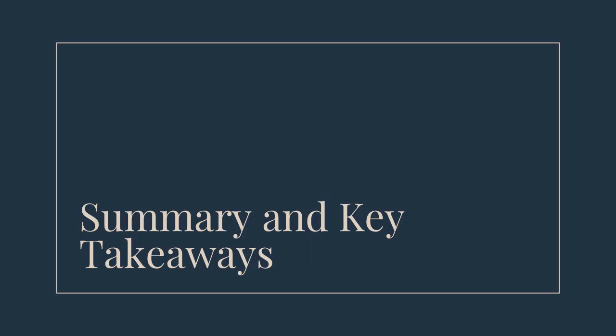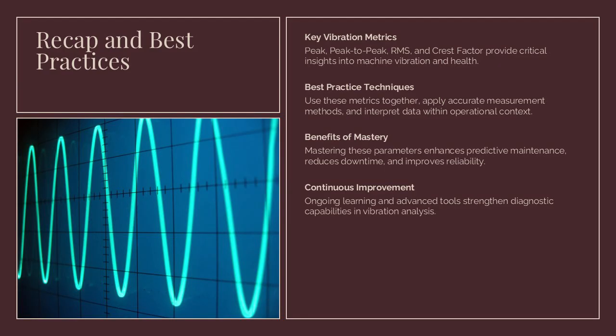Let's summarize key takeaways and best practices. Peak, peak-to-peak, RMS, and crest factor are fundamental parameters in vibration analysis, each offering unique insights into machine health. Peak detects extreme events, peak-to-peak measures total excursion, RMS reflects overall energy, and crest factor identifies waveform characteristics.